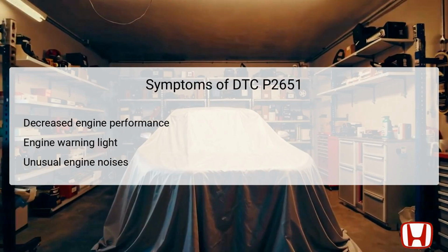When the P2651 code is present, drivers may notice several symptoms affecting vehicle performance. One of the most common indicators is decreased engine performance, which can manifest as reduced acceleration or power. This is often due to insufficient oil pressure, which affects various engine functions.